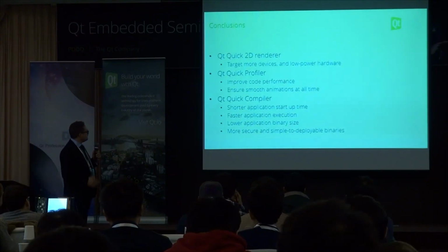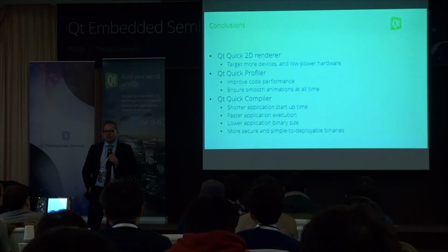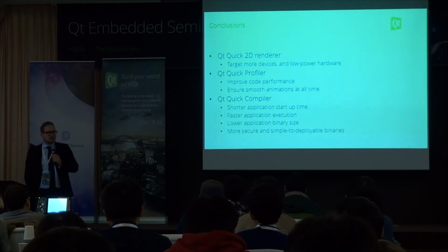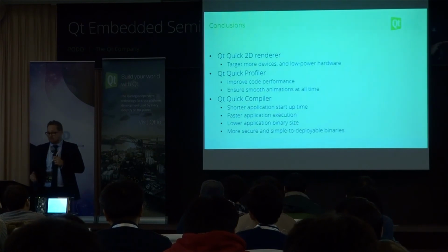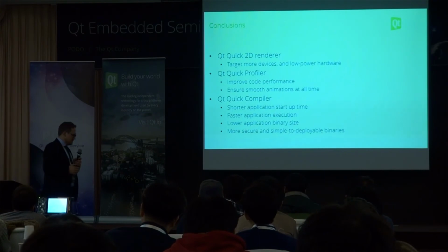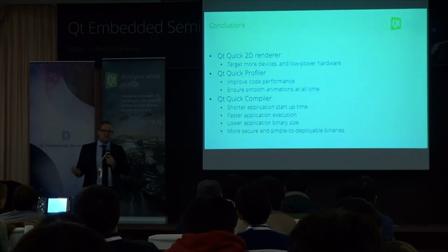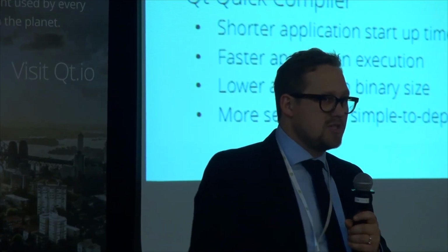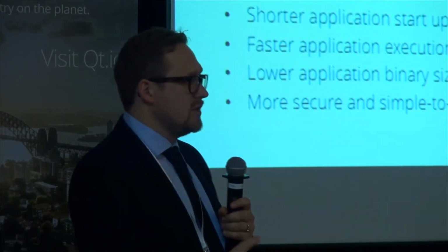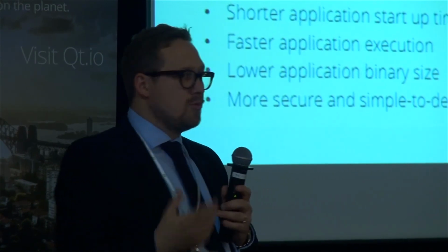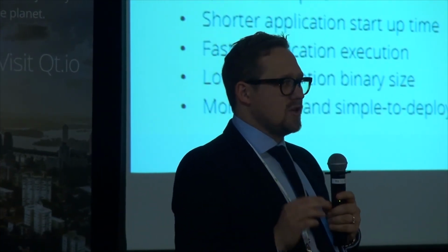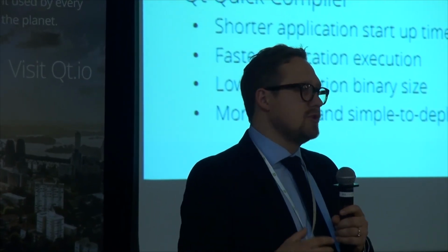And the answer is yes, you can use the Qt Quick 2D renderer. That's a feature that we have in the Qt for Device Creation package that allows you to do that very efficiently. Of course, it's very easy to implement complex OpenGL UIs in Qt, and if you have done that, the 2D renderer will not render OpenGL calls, it will not render textures, etc. So it's for more simple user interfaces.